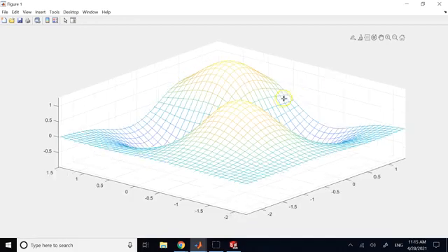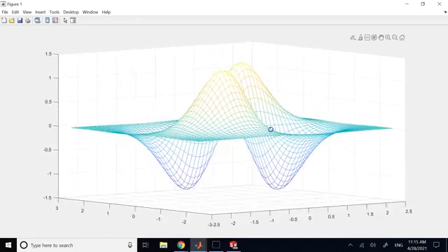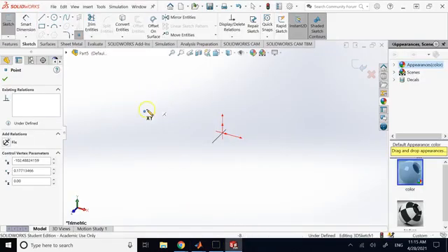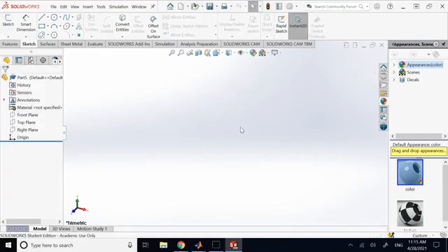Here they are connected by squares, but most of the time when you're dealing with a 3D printer, every 3 points that you see are typically connected by a triangle. And this process of connecting every 3 points that are next to each other and creating an approximate surface using a bunch of triangles or any other form of shape like these squares, we call it tessellation. So really, if you want to do tessellation, now you have to create tons of these surfaces in SolidWorks or CATIA, and that's not easy. So in general, creating something like that in a CAD software is not super easy, especially in SolidWorks and CATIA, as far as I know.